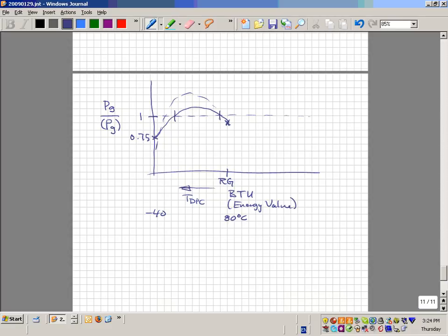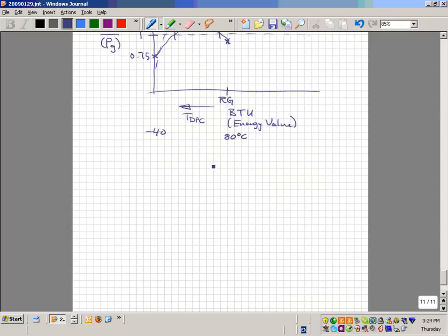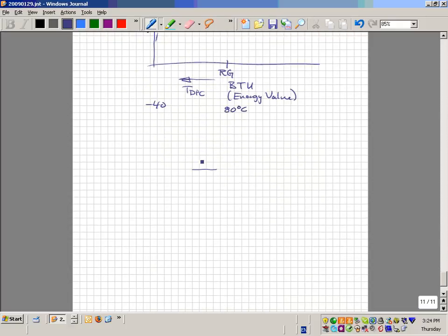Model for cost, model for revenue, everything has to be built into it. Any other suggestions about things that could be done? Alex's comment was that basically we have a 60 bar delivery pressure. That's going into the pipeline to sales. Down here we've got obviously something lower, at the point where they're taking the gas. Right now, through the pipeline we're losing 25 bars of pressure. That's a dimensioning effect. You only have 25 bars to lose. So you have to dimension the pipe accordingly because you've got a distance of 10 kilometers.